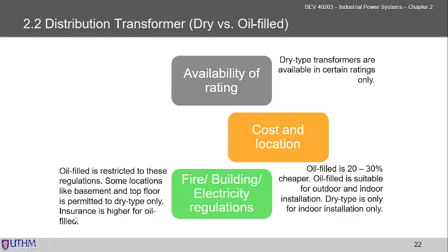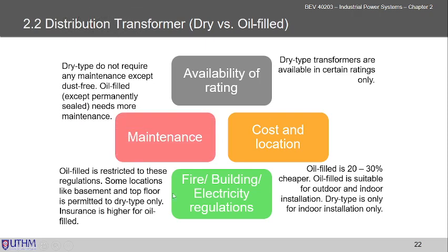So if you are using the oil types, the insurance is much higher. You need to buy a more expensive policy for your insurance. And the last one is maintenance. Of course, no doubt, the oil type needs a lot more maintenance work compared to the dry types.